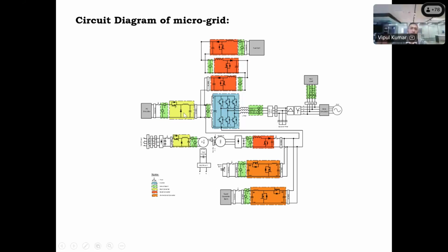For the PV buck converter, we are getting the voltage and current data before the input of the buck converter, and at the output of the buck converter we have the voltage. This data we are getting in the software based on the LEM voltage and current sensors. So that layer will manage the data.